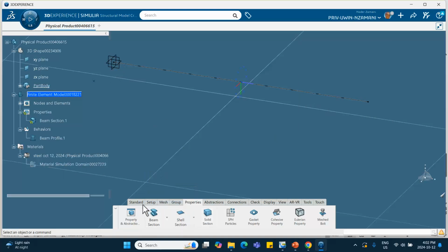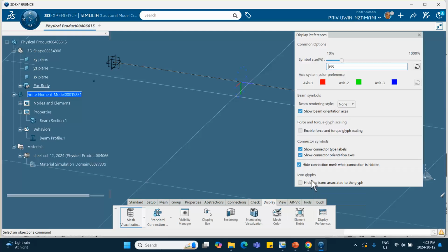Now, if I update, Control U, see this exclamation mark went away. So it did take it actually. And when you do that, you don't get any specific shape around this. The cross section looks like that. If you want, you can say display, and select it as a sketch.